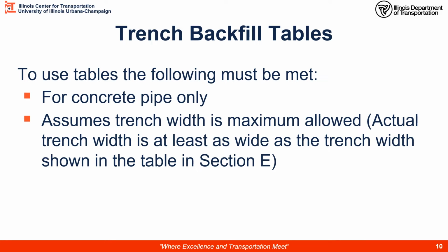It assumes that the trench width is the maximum allowed. With depth, the trench has to be certain widths, and if that trench is that width or wider, then these tables work for calculating the trench backfill as presented in section E.